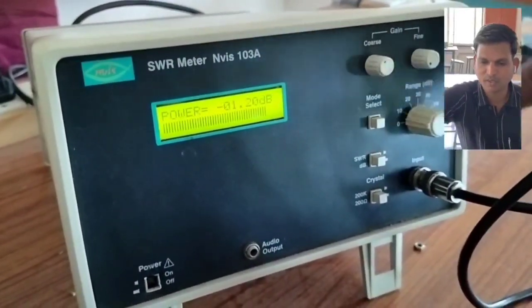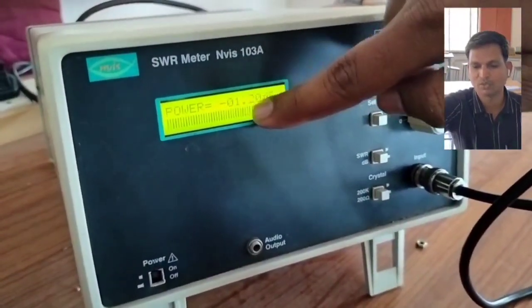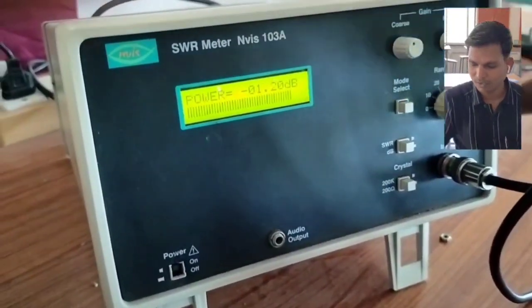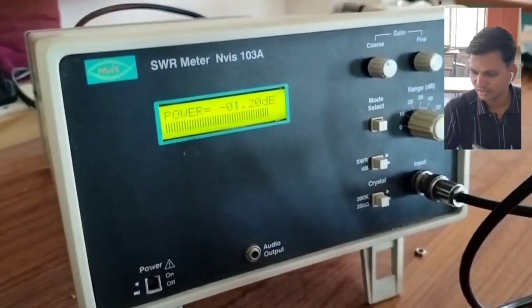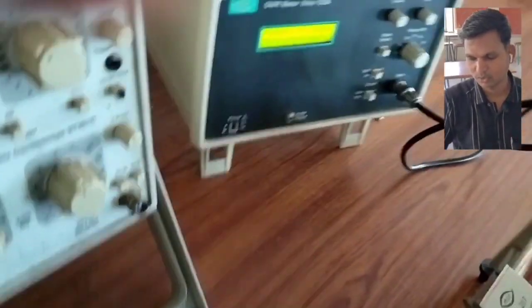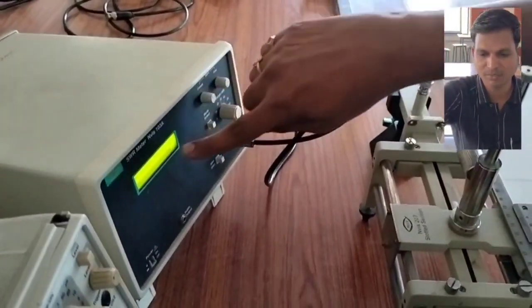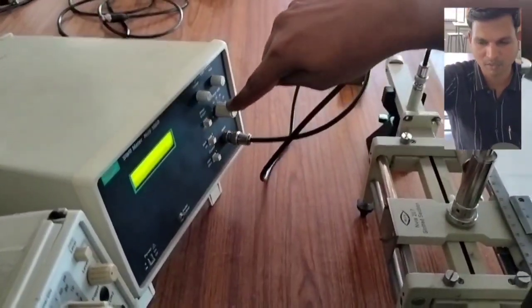We need to add these two values. So 60 plus 1.20, 61.20. Okay, that is the value without the directional coupler. Up to now we have not connected any directional coupler. Without the directional coupler, the power we are getting is 61.20 decibel. This is nothing but the P1 value.